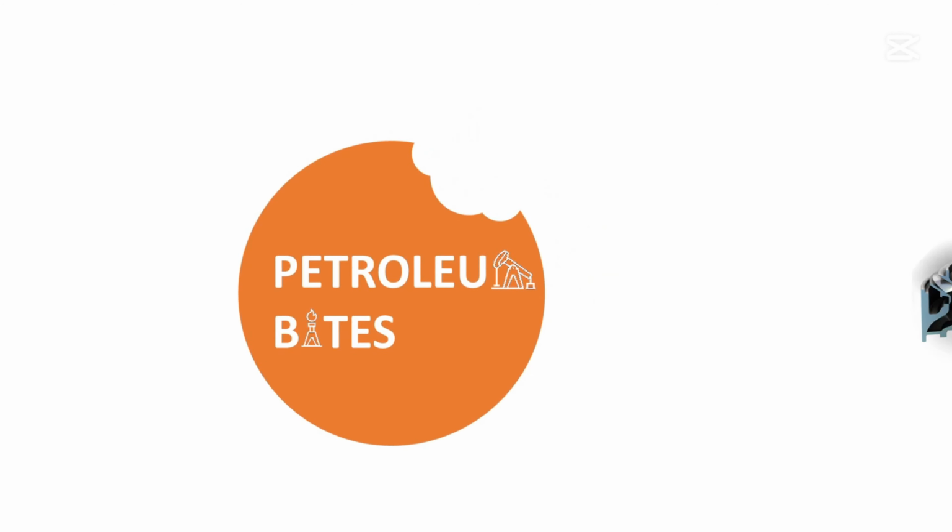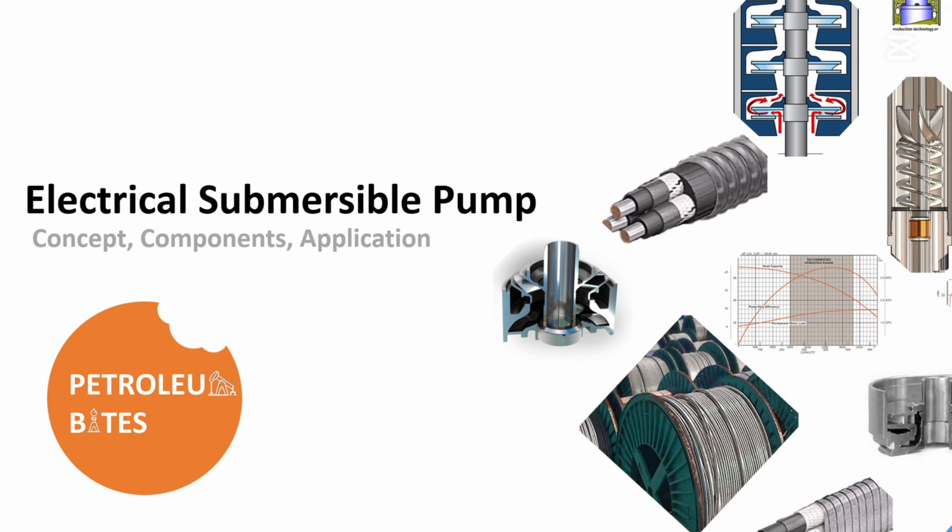Today we'll explore one of the most important artificial lift methods in the oil industry, the Electrical Submersible Pump (ESP). In this lesson we'll begin by developing a broad understanding of artificial lift methods and the well conditions that require their installation. We will then take an in-depth look at the ESP system, examining its lifting mechanism and how it builds pressure through multiple pump stages to efficiently move fluids to the surface.